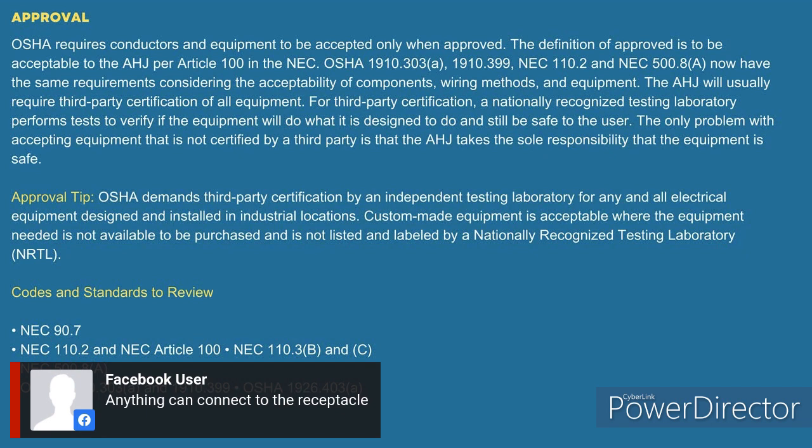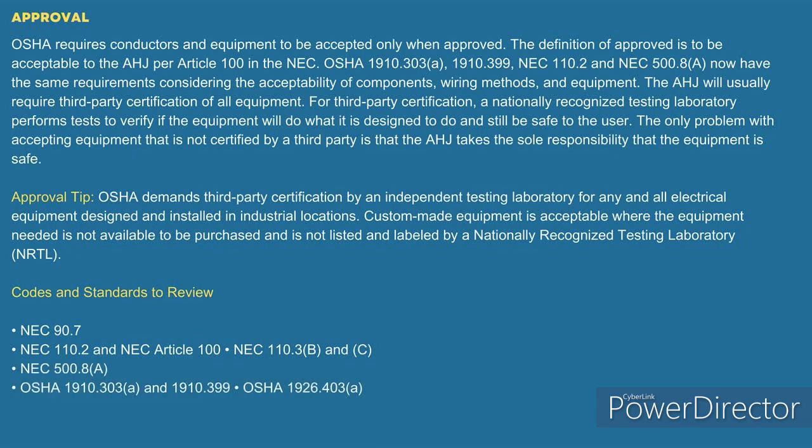Okay. I see what you're saying, Justin. That anything can connect to the receptacle. So if it's in that location, then you need to make sure the receptacle is Class A protected. I 100% agree with that. Okay. Then it says they now have the same requirements considering, listen to this, the acceptability of components, wiring methods, and equipment. Now, let me explain this.